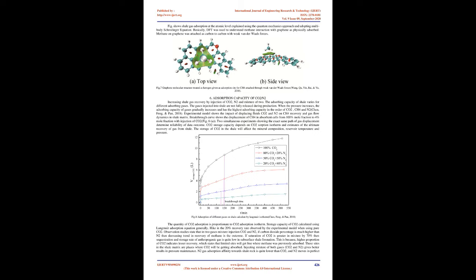Hence, methane gas as a free gas desorbed from the shale surface comes out of the outlet valve. The gas composition coming out of the adsorption chambers in the experimental model is collected in a mass flow collector, and the composition percentage is calculated by gas chromatograph. Experiments stop when the mole fraction of methane reduces to 2% in the samples.